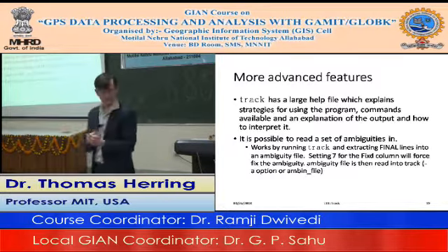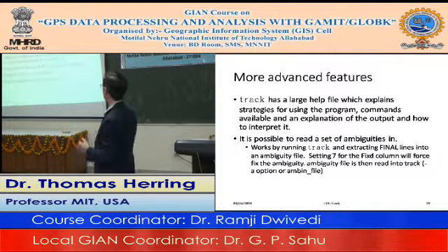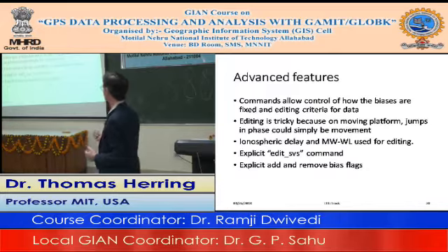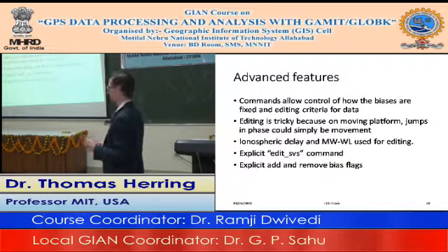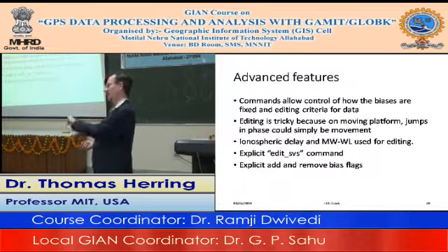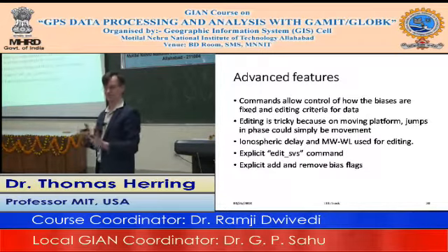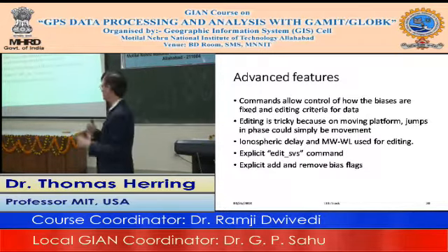So, some of the advanced features that people tend to use: as I said, there are lots and lots of options you can use here. The biggest things people end up changing are the ionospheric constraints that are used and the weights for the Melbourne-Wübbena wide lane. There is actually an explicit ability to delete data. We've certainly had cases of kinematic receivers where one of the satellites is, for some reason, very poor quality, and we just delete it completely. Sometimes it's not in the ephemeris, which can be an issue.